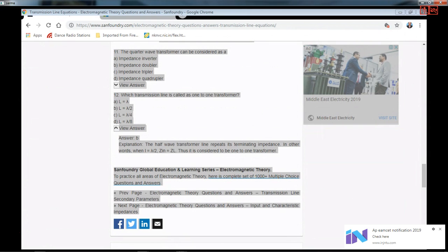By measuring the VSWR of a given load, and something else, you are going to determine what the load is, that is, you are going to estimate the ZL value of the load that is given. And VSWR meters are present in all these labs, which cost just around 10,000 rupees or so, compared to a network analyzer, which would cost you around lakhs of rupees. So that's the significance of introducing this capital S, the VSWR.